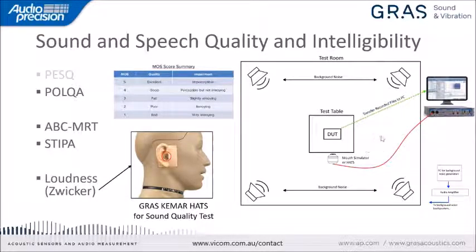But I think it's important to know that the APX 500 software made by Audio Precision offers the possibility of performing tests such as PESQ and POLQA. The APX also incorporates the possibility of performing a speech intelligibility test that follows the ABC MRT and the STIPA test.